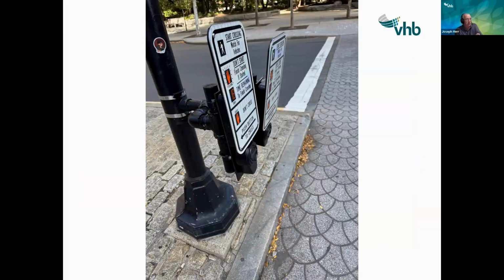This particular photo is 2 buttons as well, but they're aligned on the same plane along the curb line. This is at a median, and one button would be for one approach and one for the other approach. This one happens to have 2 concurrent crossings. This is an exclusive PED, so this button would be for the crossing at the top, and this button at the bottom. You can see this button assembly has sort of tilted down a little bit to the pole.